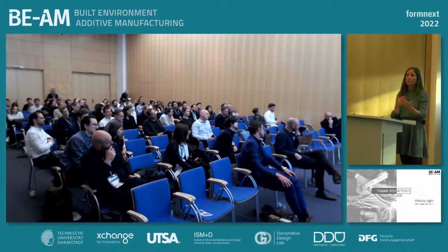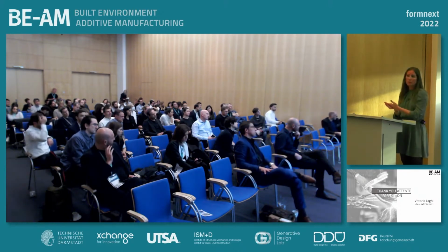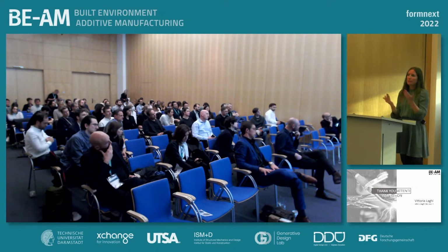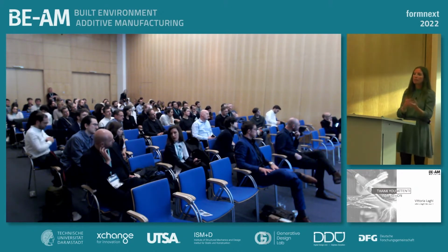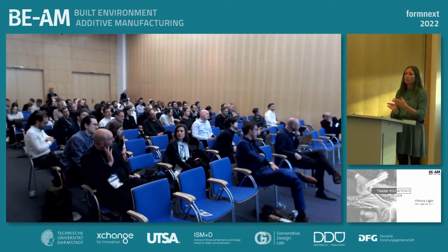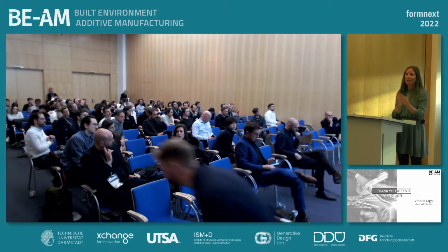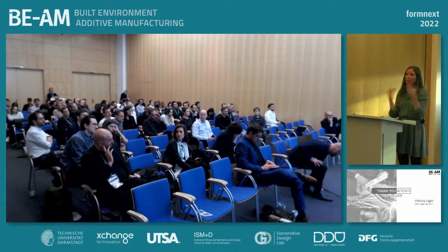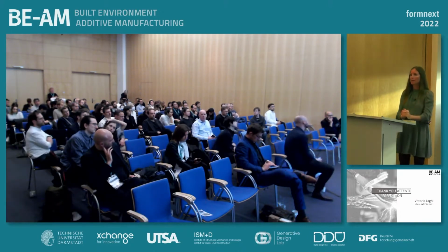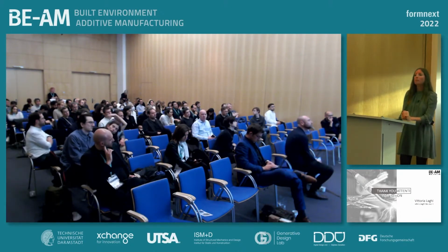And so you can optimize that, and so you're reducing also the printing time. But yeah, for sure, there could be limitations that can be also overcome quite easily. So you can maybe weld pieces together afterwards. And so you can actually increase the scale of your printed part even more.